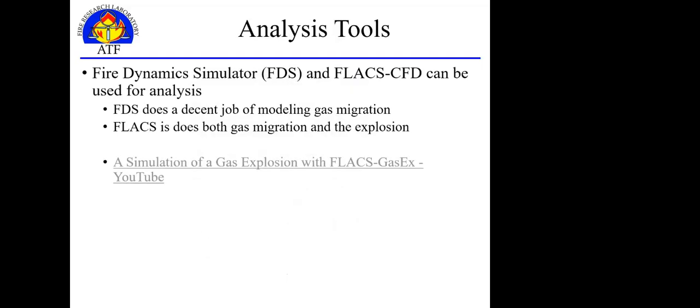So some other tools that can be useful are hand calculations and advanced computer modeling. From a hand calculation standpoint, we can do some very general rough calculations, say just something as simple as, I've got a 20-pound propane cylinder in my structure. Is the contents of that cylinder even enough to get to an explosive mixture? You can determine that based off of the volume of available fuel versus the volume of the enclosure.